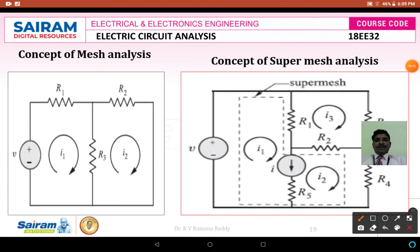As we know very clearly, the mesh analysis and its steps, how to apply and how to find the unknown loop current. The figure I am showing here consists of one voltage source and the resistances R1, R2, R3, all connected in a T-section manner in two loops. In these two loops we analyze the two currents as I1 and I2, taking I1 and I2 as references flowing in the clockwise direction, as I am showing in these two loops.